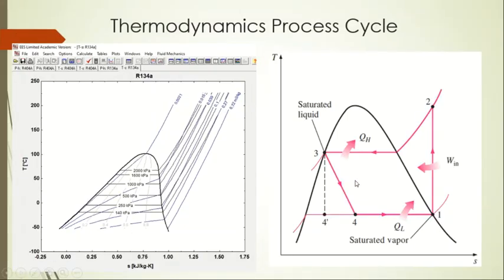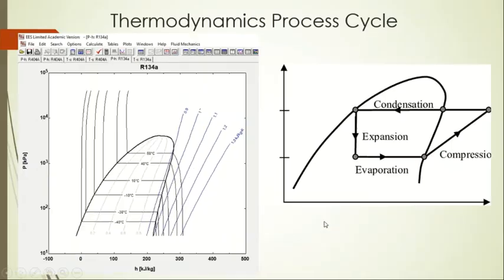So what we come to know from this diagram is that the evaporator is an isothermal process, because temperature does not change at all from initial to final position across this process. On the other hand, if we see the evaporator in this diagram as well, the pressure is constant, so we can also say that the evaporator is a constant pressure process as well.